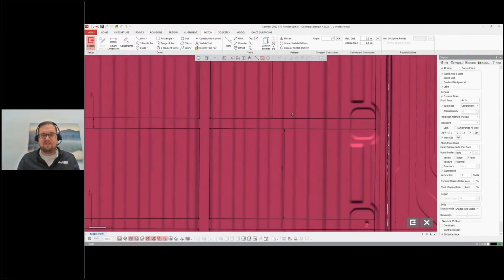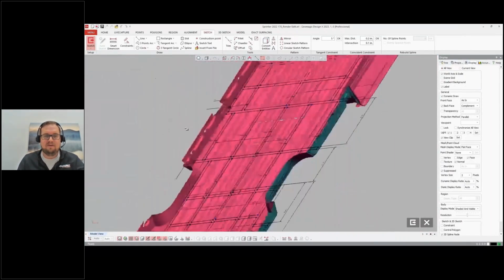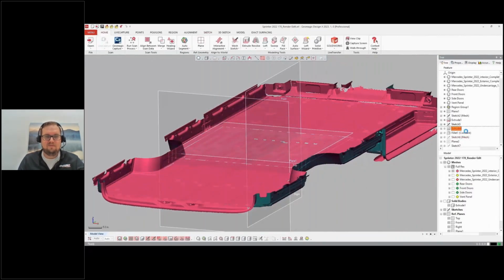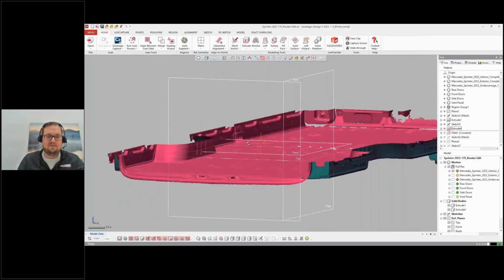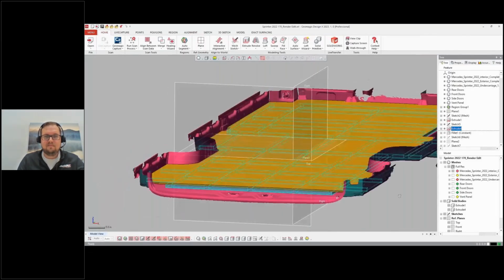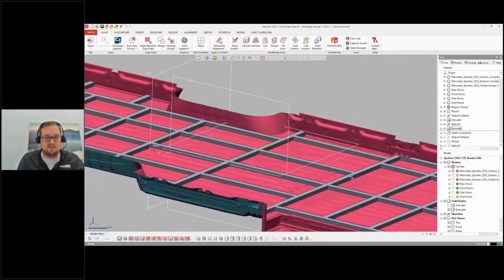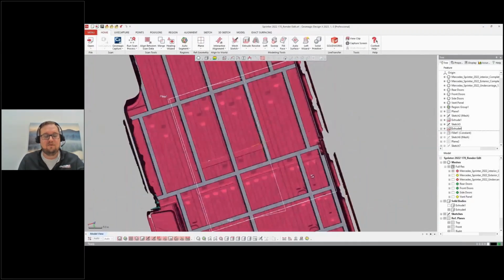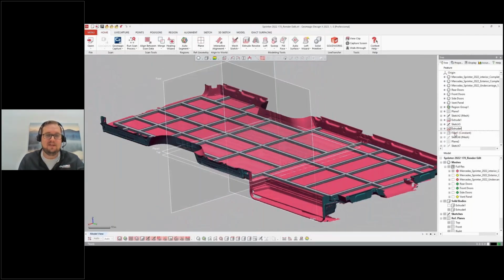But it also gives us this large area for mounting things like cabinets to a very solid base, as well as giving us this offset. Once I complete my extrude here, you can see I can bump this up into solid bodies and create that frame. If I wanted to, say, bring this into SolidWorks or do a live transfer to SolidWorks, I could create cut lists for this for weldments. I can also create a 2D CNC path for my floor from just a DXF of that sketch.